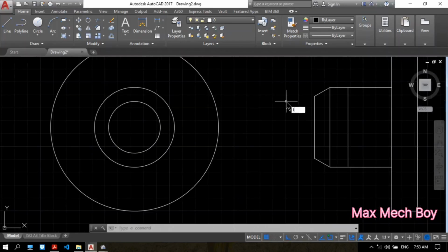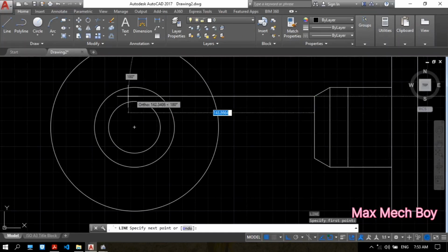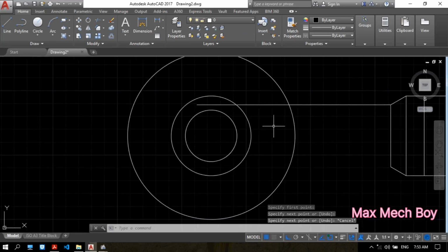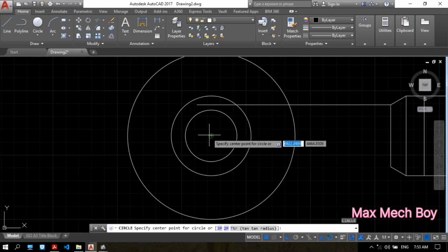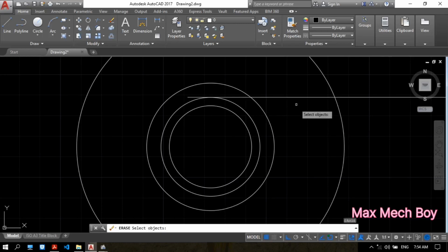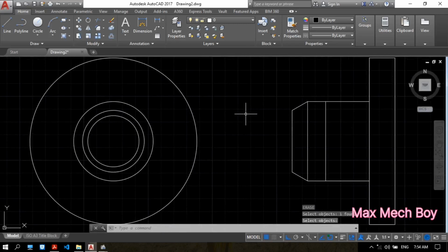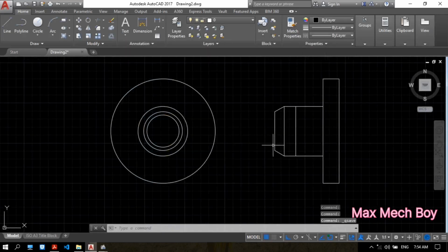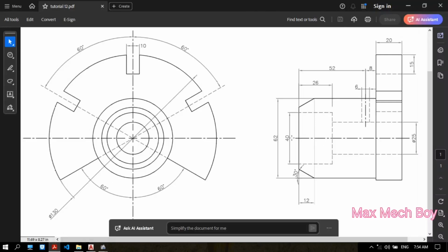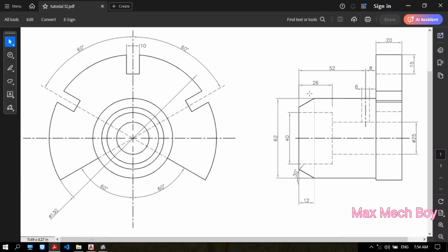Now you need the view here. Click. Yes, you will need the side view here for the taper angle. Erase line. Okay. Save. Okay, now you will make a hole here, a 26 millimeter deep hole, a 40 diameter hole.